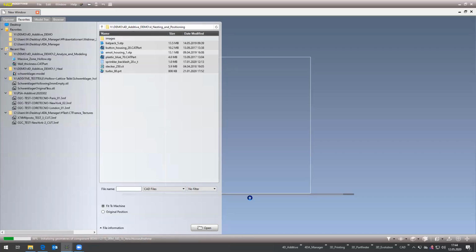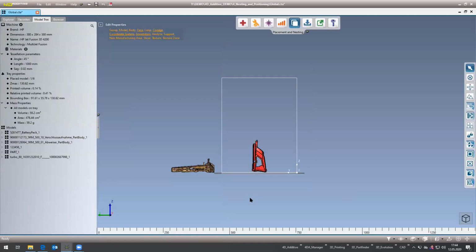you have, which is the BREP model, not the STL or the tessellated model, and run that through an FEA analysis. So the support structures and the hollowing wouldn't be included in that CAE analysis, so you would still end up with your original model. You might end up with something very similar to the resulted data set that Laurent did when he checked the model to see that there was weakness in the specific wall.